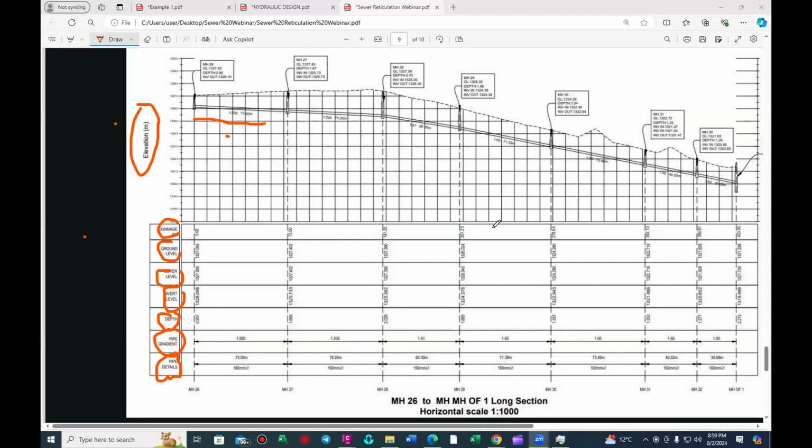Then there's Jerome. How do you determine your slope, your diameter? Do you use the lowest value, then optimize it that way? So like I said, first of all, you start with the preliminary design. So you actually design it in Civil 3D. You draw it, you do your sewer layout, you do your profile views. Then you take those slopes. You'll be using your mind, because this is where you have to be present. Like I said, Civil 3D does not design, you design.